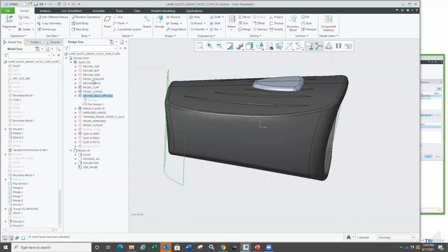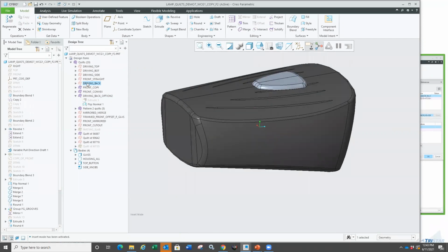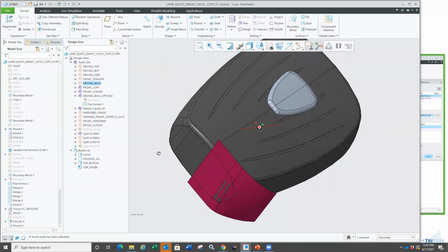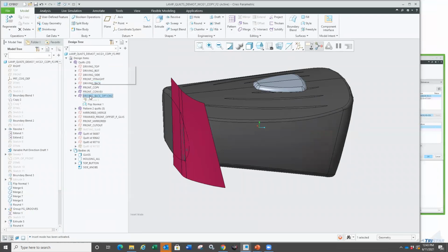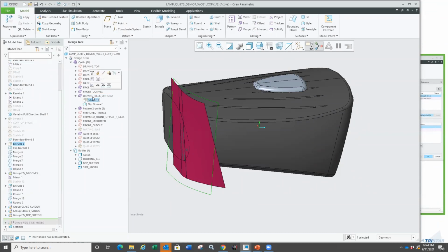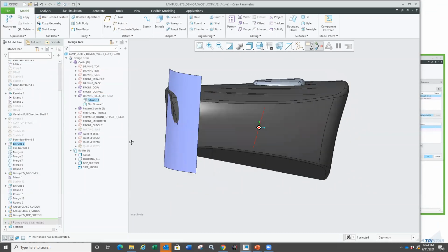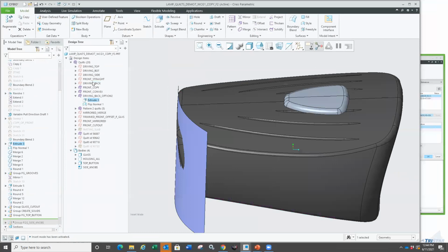So it looks like, let's see what I used here, right? I used this driving back surface in here. Let me just say, show me the snapshot. So to create that back surface, looks like I've used this, right? It's amazing how that snapshot is really helping me. I didn't have to go insert mode all the way up to see how it was done, right? Now I can just go back to, let's say this is the one, right? I do have another surface that I've hidden, and there it is, right? So let me just go back and do my snapshot.